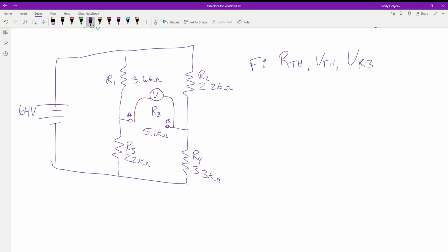So we start at point A and we go around. Well, we come here, which direction do we go? Doesn't matter. It'll work either way. Okay, what's the polarity of these resistors when they're hooked up like this? Positive to negative from the top. Because this is where our battery is, it's going to charge positive over to here. This is going to have less potential. This is going to be a positive, this is going to be a negative. Same with this guy.